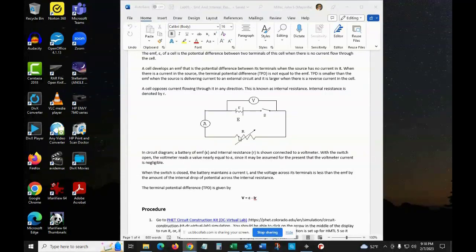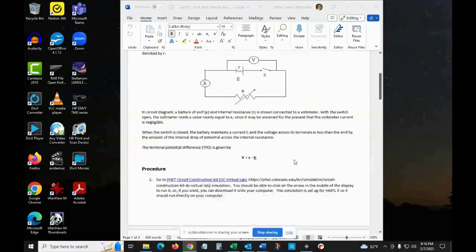What we're going to explore is the observation that batteries have a finite lifetime. The relationship between the EMF, the voltage, and the current going through the resistance is given by the expression terminal voltage V is equal to EMF epsilon minus the product of current I times r. Here, small r is called the internal resistance, and the product Ir represents the energy losses internal to the battery once it is connected to the circuit. So r is not a physical resistor inside the voltage source.